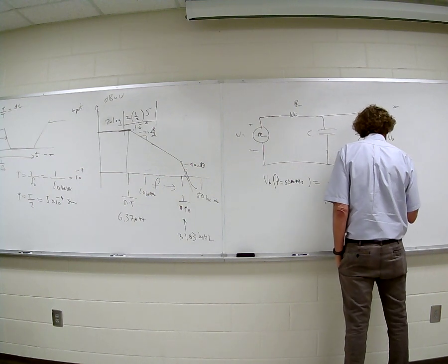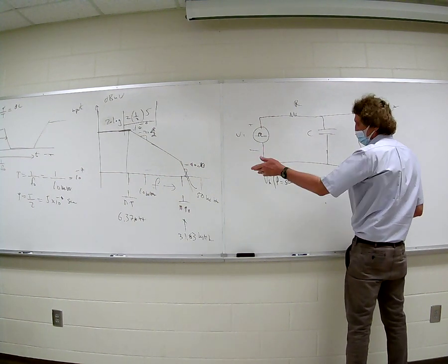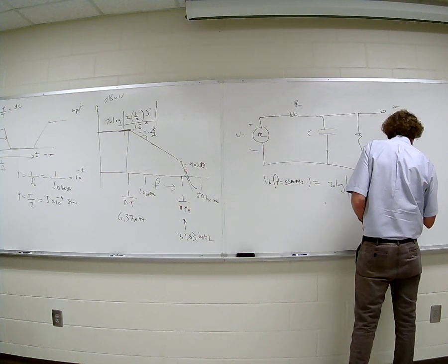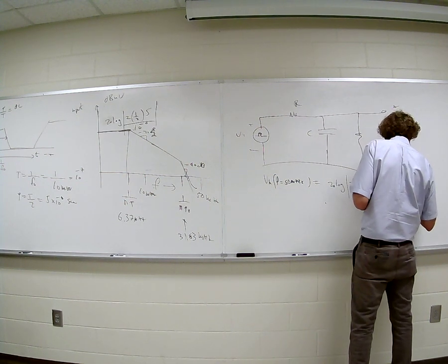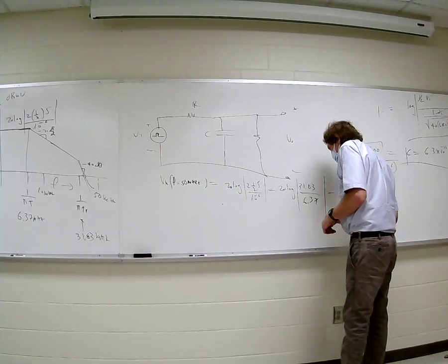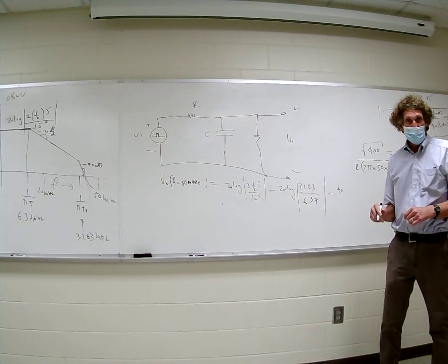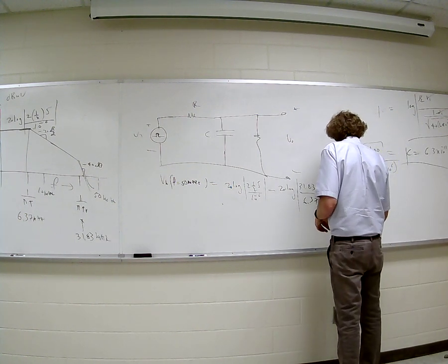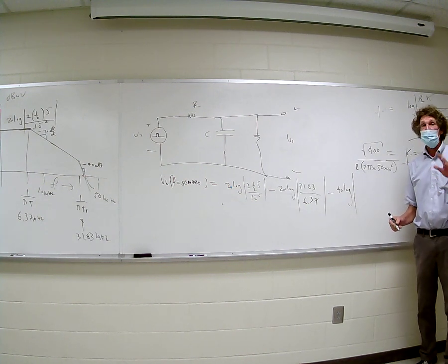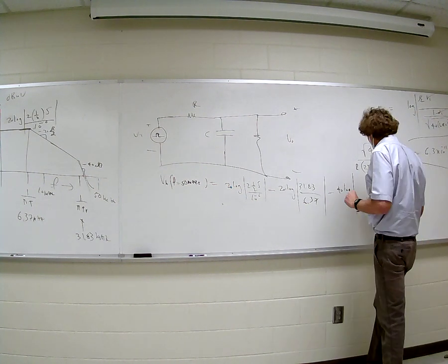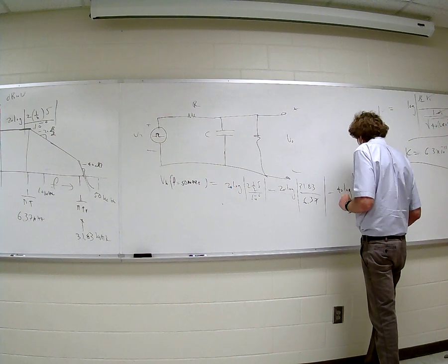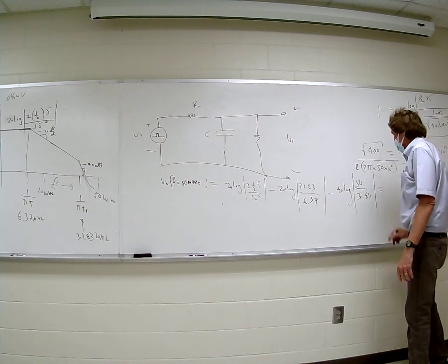Then it's minus 20 times the log of the upper frequency, which is 31.83, over the lower, which is 6.37, right? And then we get to the higher one. Then it starts falling at 40 dB per decade. Do you agree with that? 40 times the log of what? Well, the output of 50 megahertz. Yeah? 50 over 31.83. That's right. And that would be the input's value of voltage at that frequency.